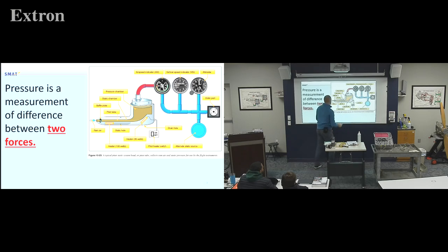If I want to check if there's a leak between those 2 points or those 2 systems, I can run a vacuum on here and then plug it and see if the pressure stays where it's at. Now actually I said that backwards, excuse me, I take that back, I'm on the wrong side. I can add a little bit of pressure on this side. If I ran a vacuum over there, it'd be a problem.